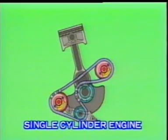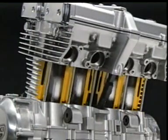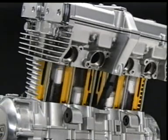In other engine designs, such as the parallel twin or the single cylinder, a counterbalance shaft is used not only to balance the movement of the reciprocating parts, but also to counteract the horizontal inertia forces as well. If the engine is designed to take all these factors into consideration, it will run smoothly.